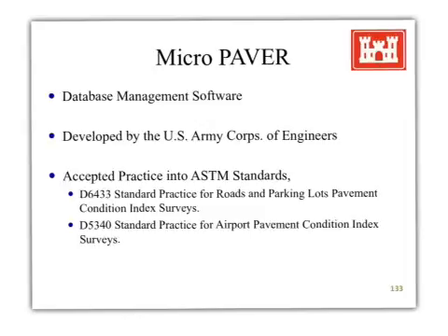The first one is D6433, which is the standard practice for roads and parking lots pavement condition index surveys, as well as D5340, which is the standard practice for airport pavement condition index surveys.